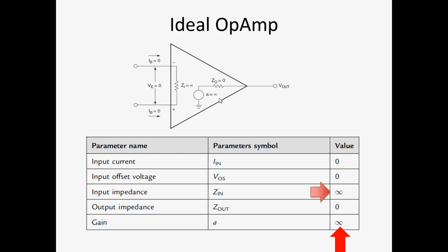Now things add up and you understand the issue with contact impedances and not preparing the skin and the electrodes well. The electrode drift, the half-cell potential of the electrodes, will get amplified by the gain of your amplifier. Well, not entirely, of course. But if those things change, you see that the EEGs go all over the place.